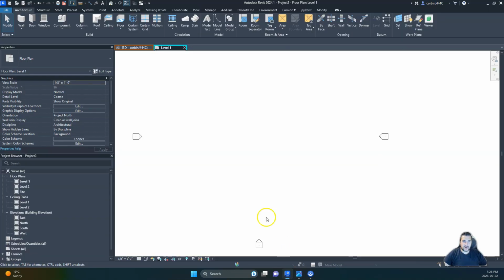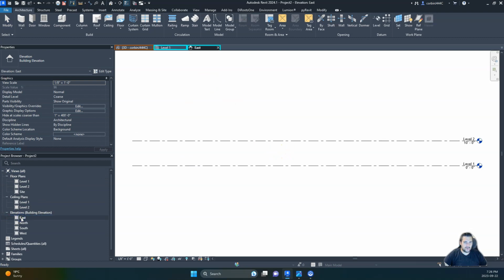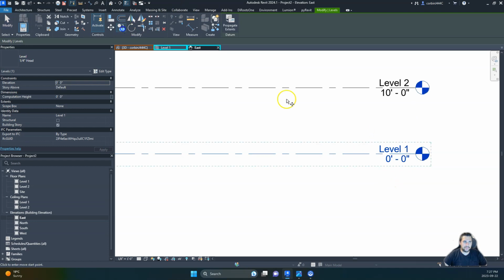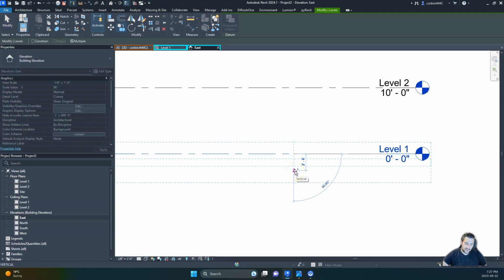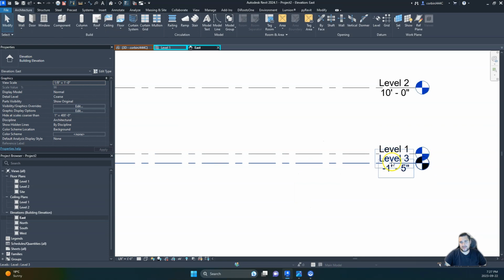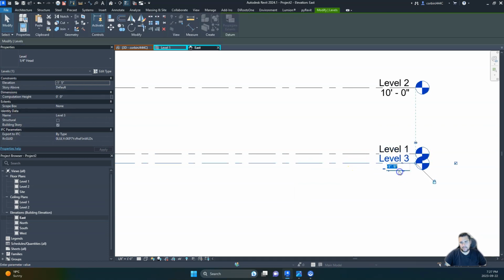So, to talk about modeling of the structure. I've got a blank project open here, and what I usually start off with, and we have this built into our template, is we drop a level down. Is it 15 inches, I believe? I'll check that in a second. Sorry, it's 1 foot 3. And we'll just call this top of piles.